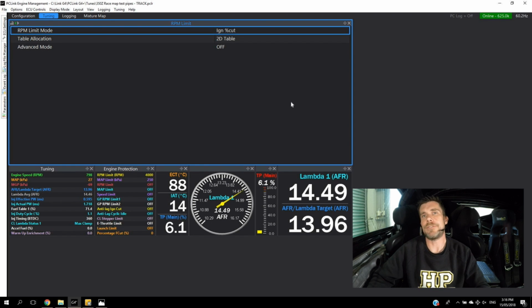So this has the effect of, first of all, cutting the ignition, so we're sending unburned fuel and air charge out into the exhaust system, but then it's also coupling the cylinders that are still firing with a lot of ignition retard, so that the combustion process is still occurring very late in the engine cycle and out into the exhaust stroke. So this actually then has the effect of combusting the remaining fuel and air charge out in the exhaust system. So on the plus side, this is a great way of spooling a really large turbocharger.